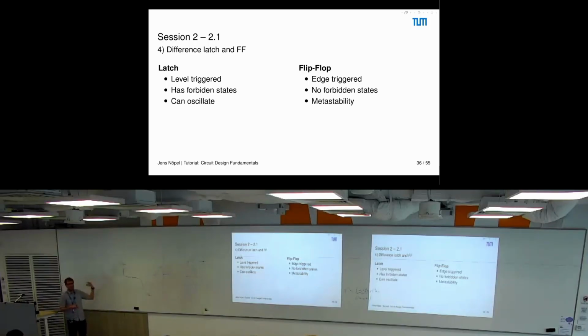But that would be in an ideal world. Since we are not in an ideal world, there are environmental influences. At some point in time, you would shift slightly to the left or to the right, and then you end up either in this direction or in that direction. But you don't know in which direction it is going, right? So this is how metastability can be explained.